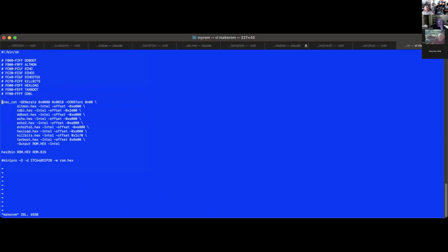I think I had a problem doing offsets, getting it to do what I wanted with hex files. So I run it through SREC. I just make my ROMs, and then I figured out what all the offsets are supposed to be based on where I want them in the ROM. Then I SREC the hex files, do the offsets here, and then I just combine them all into one hex file. I did have a problem with offsets in hex files, I think.